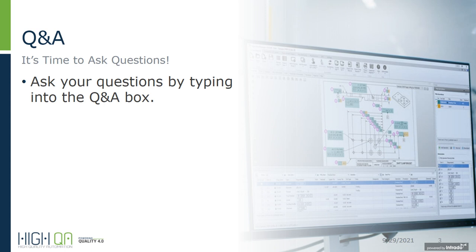Can drawings be loaded onto the HiQA system instead of built within the HiQA system? Yeah, so the drawings are uploaded as, let's say, PDFs or TIFF files or even JPEGs. Some of our customers use JPEGs. Typically, you're collecting them from your customer, either in job shop format, the customer sends you a drawing, or maybe you have a design team internally that produces drawings or 3D models. But you upload those into the system, that kicks off the part record creation, and then you're able to automatically balloon those and start building inspection plans from there.